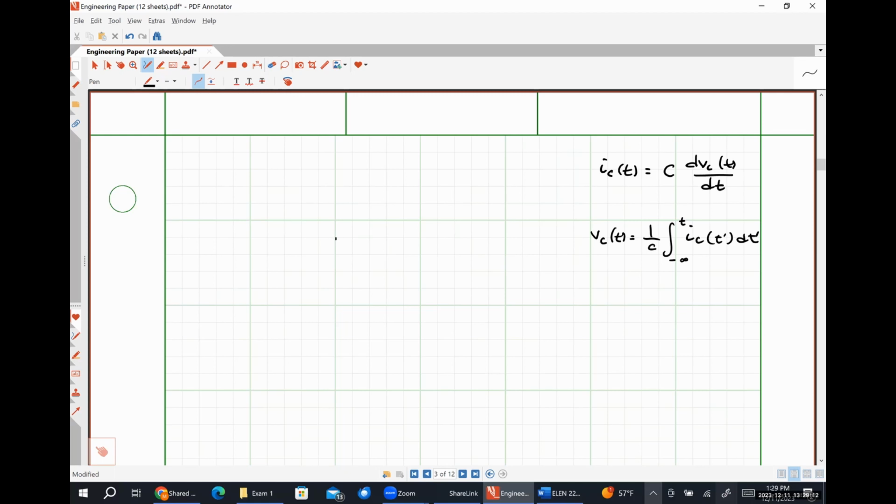But effectively, all we have is an inverting amplifier. But we're going to have a capacitor in the position of one of our resistors. So let's start by putting the capacitor here. So here's C. I'm going to put my resistance up here.